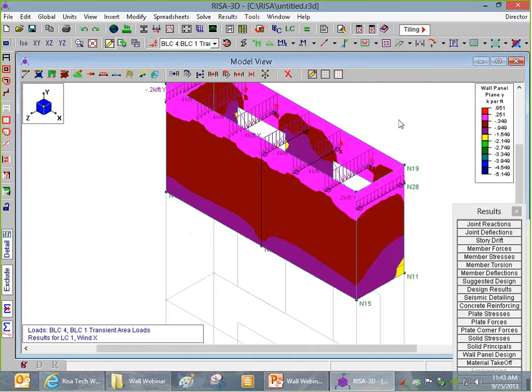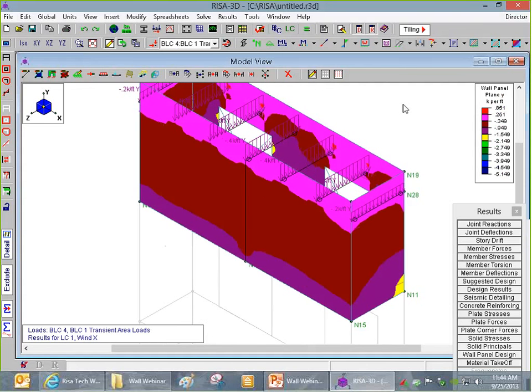And so in that case, because we went from about 1.2 kips down to about 0.7 kips, we can see that the wall in this case is maybe about 40% less stiff than the column, but it is going to pick up, say, 40% of the load in that case.